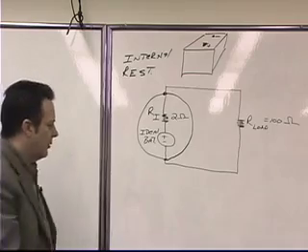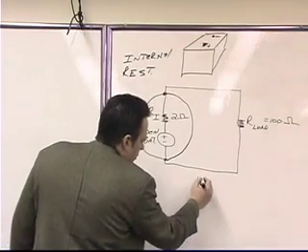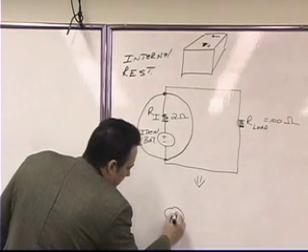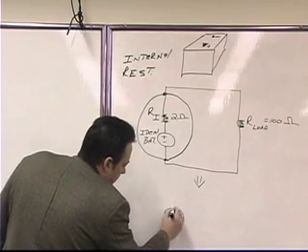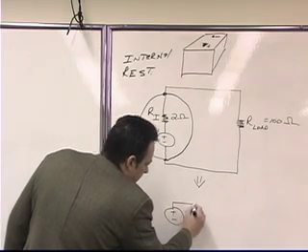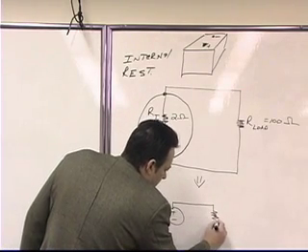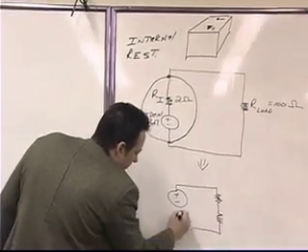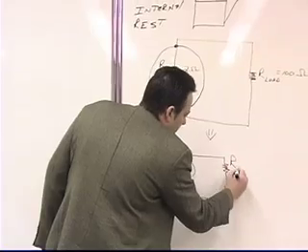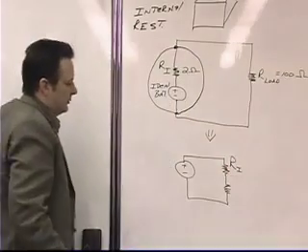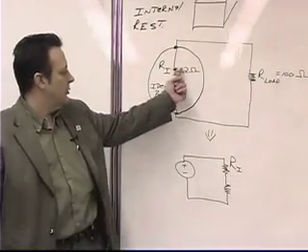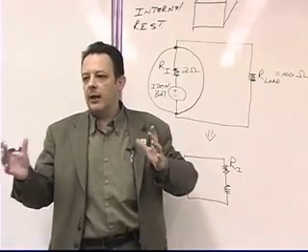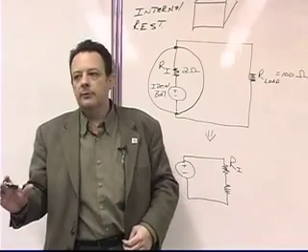So we are going to simplify this circuit by drawing it the way that we're used to seeing it, where we have an ideal source, and then we have a resistor in series with another resistor. This resistor is going to be our internal resistor. Now, does it matter that we moved our internal resistor outside of the box for the purpose of doing the analysis? It makes no difference whatsoever.